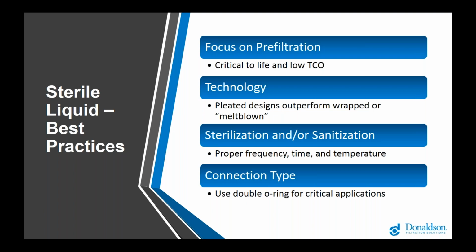that really matters. So the first O-ring on those elements is really used to clean that sealing area so that when the second O-ring makes contact with the housing, it's really going to have a perfect and uncompromised seal. So I would say that's one of the most important ones.